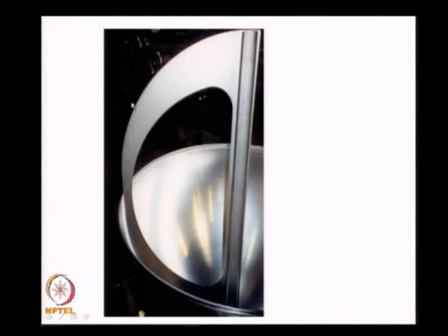This is the vane that I am talking of, this is the gap that I am talking of, this is where the sieve is, which collects the propellant and feeds it into the chamber. These devices have high values of expulsion efficiencies, that is, most of the propellant can be expelled, unlike in the case of the positive expulsion system. This is all about surface tension devices.